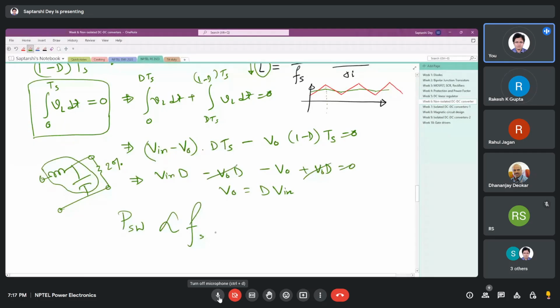Increasing frequency means the switching phenomenon is happening again and again, faster, and the same losses are happening faster. So we have more loss. So increasing frequency comes with this drawback. So what is the frequency trade-off? By increasing the frequency, you are saving space in terms of lower values of L and C.